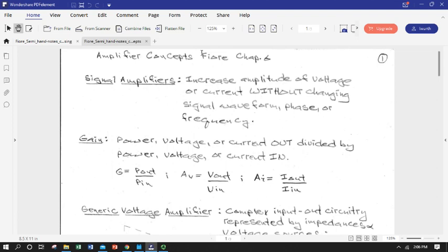So remember, biasing is what we do to ensure that our forward bias voltage at our base emitter junction is satisfied, and we don't have to use our input signal, which may be much less than that forward bias voltage necessary to open the transistor and actually draw current and amplify the signal. So we've basically been touching on aspects of amplification in the context of bipolar junction transistors.